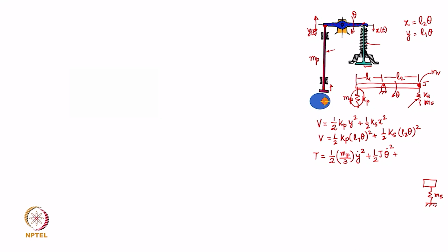That valve is not getting compressed, so it is assumed rigid. So, the mass of this valve, the cyan colored valve rod that you are observing here, will contribute without any change. So, mass of the valve times what? X dot squared. The velocity of the valve at the tip here and at this point are identical; it does not deflect. So, the value of the velocity is the same.